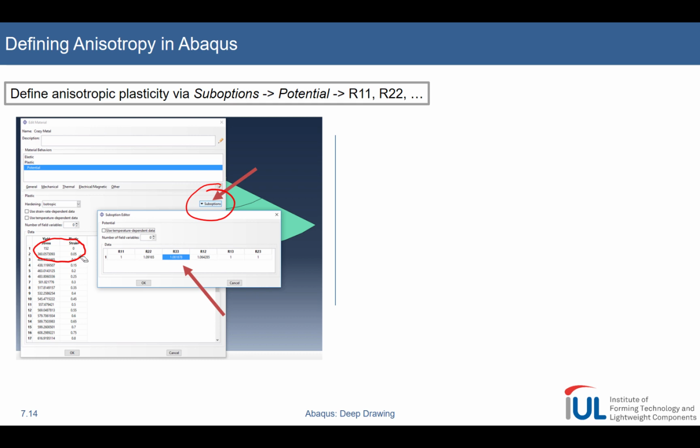So actually in the first part of these typical material models that are based on Ludwig's equation and similar equations, you should refine the first strain interval and maybe do 0.005 or 0.01 steps so that you depict this initial curvature correctly and more precisely than how I did it here. So that's just a side note.